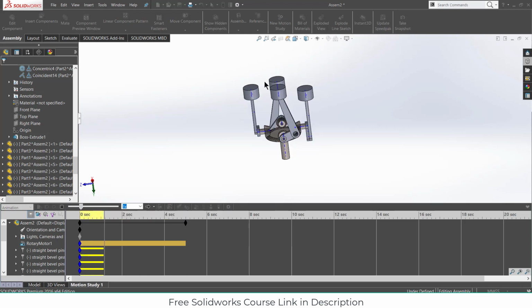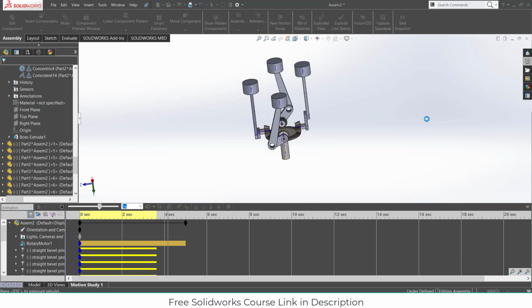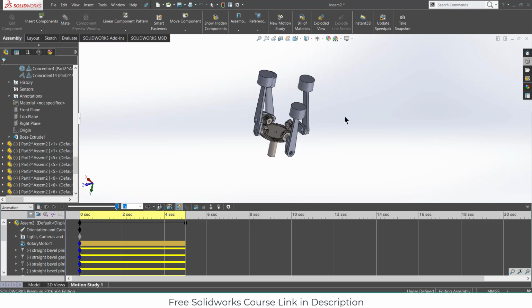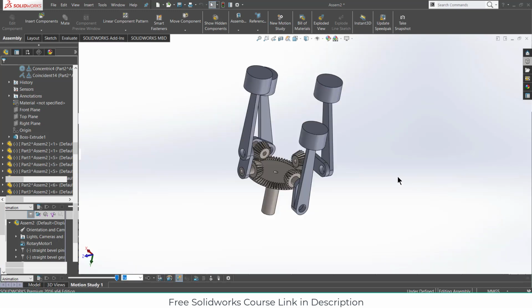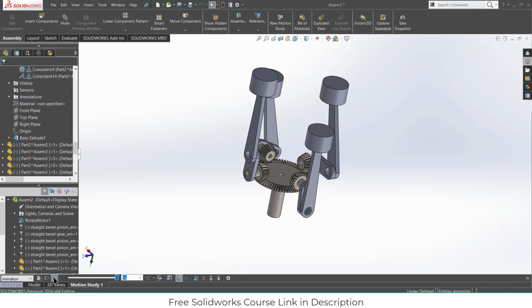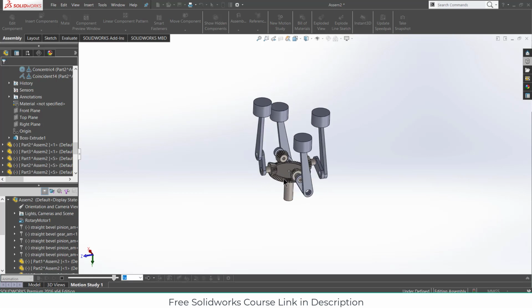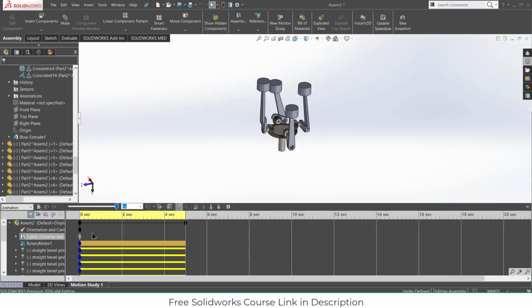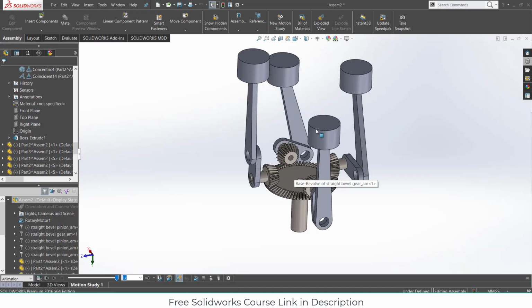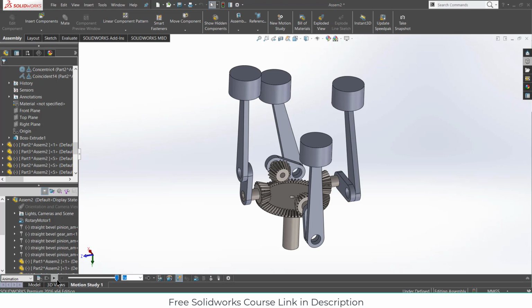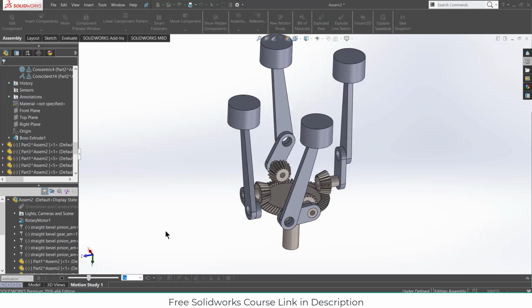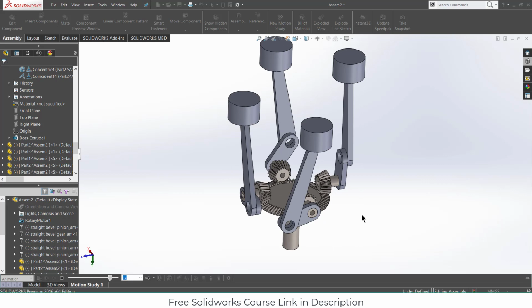So here you can see now it is working properly. So hide the library access, move it downward. So click on play. So as you can see, this is how an axial engine works. So right click on it, disable the orientation so that we can view the perfect view. So yeah, this is the perfect one. So here you can see the animation. You can see gear meshing.